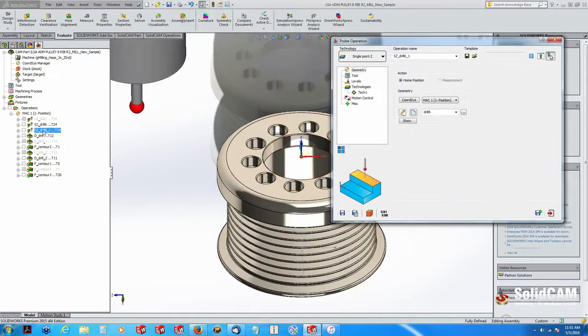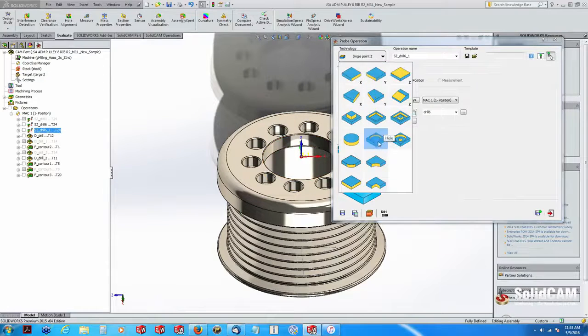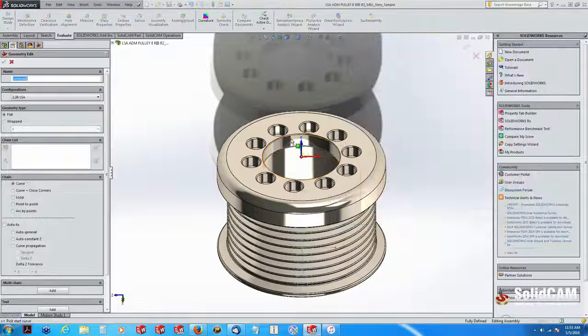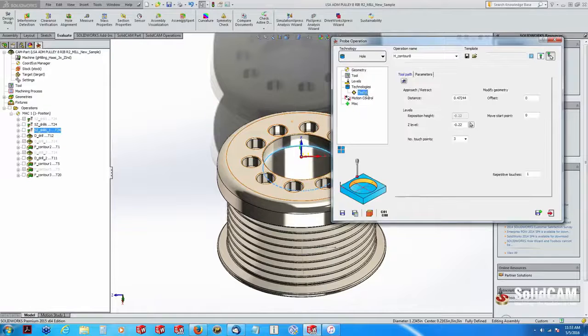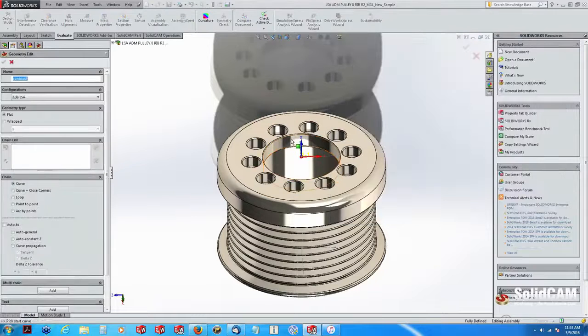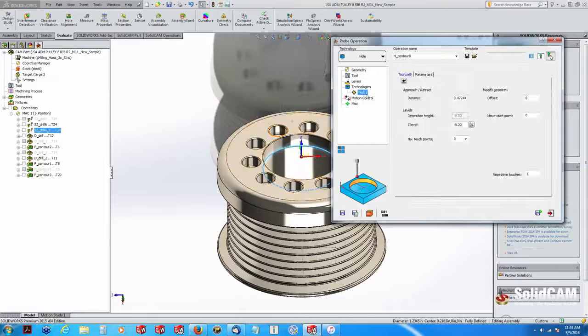So once we've finished our single Z point and I want to go ahead and add my second probe operation, which will be in this pocket, instead of exiting out, which you could do, and restarting that process all over again, we can just simply copy and see how it brings in another toolpath right there. And the important thing is to change your feature to, in this case, a hole, and then from here I'm going to select new geometry, which is going to be in this pocket.